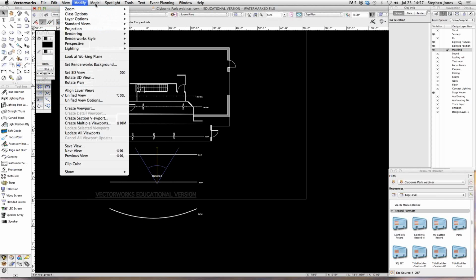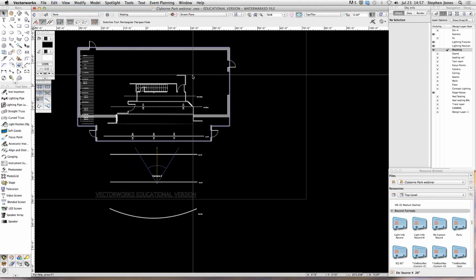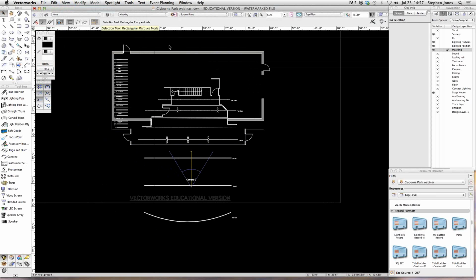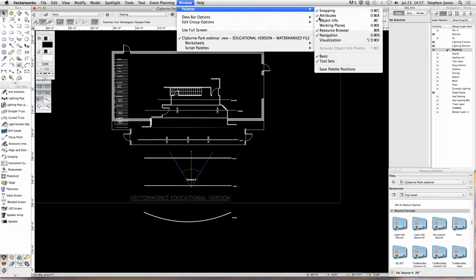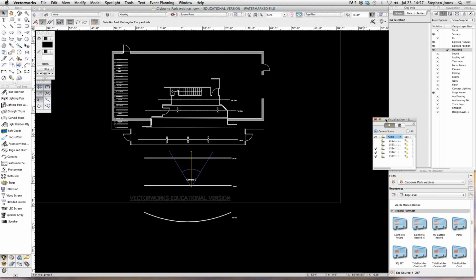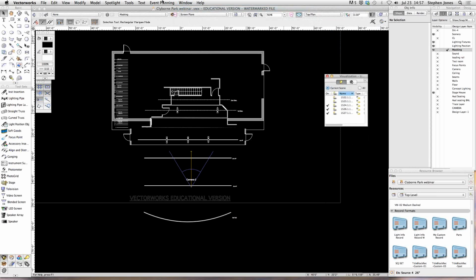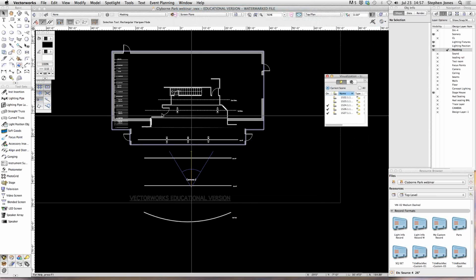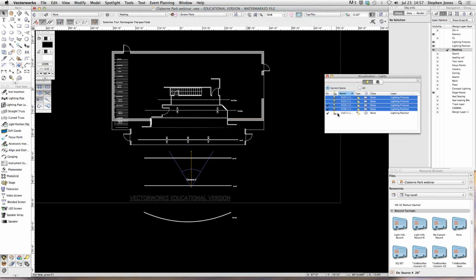And the other part of the question is, can we get live reports and sheets from the conceptual lighting workspace? You absolutely can. Let me just show you right here. Under palettes, there is a visualization toolbar. Again, under Window, Palettes, Visualization, and this would apply even under the conceptual. Every lighting fixture that you have appears in this window, and so you can actually pull and generate reports from this.